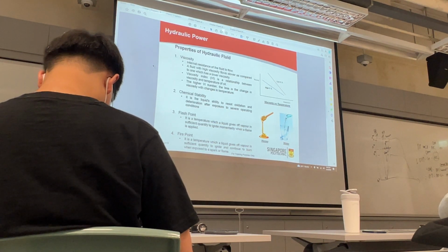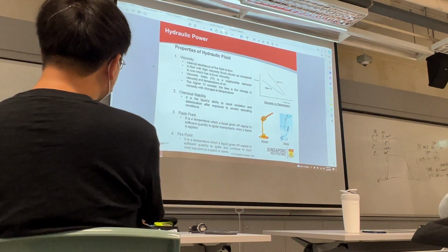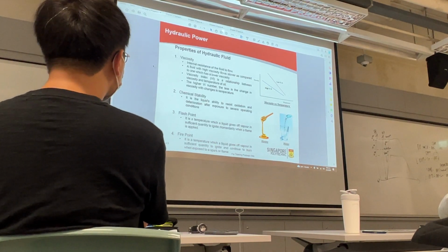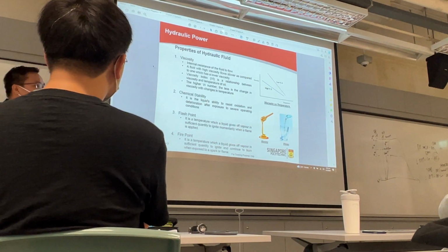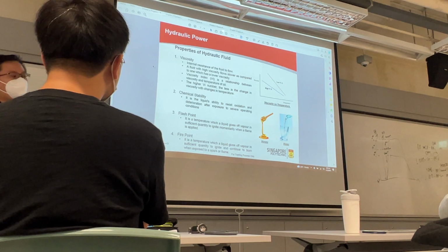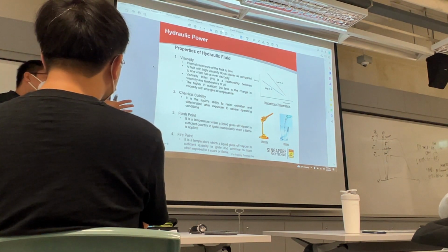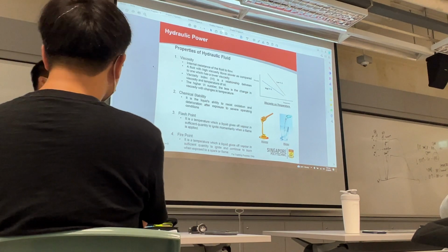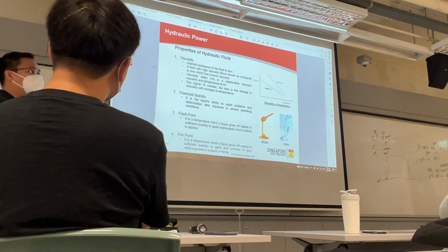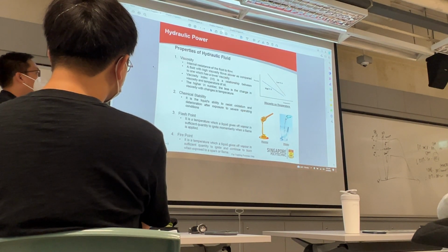Why? Now, if hydraulic piping goes around the vicinity of the engine and one of the pipes bursts, the hydraulic fluid will hit the engine bay. Engine surfaces, what is the temperature? 800 over degrees Celsius or not higher. Will it catch fire? Yes, if the condition is right.